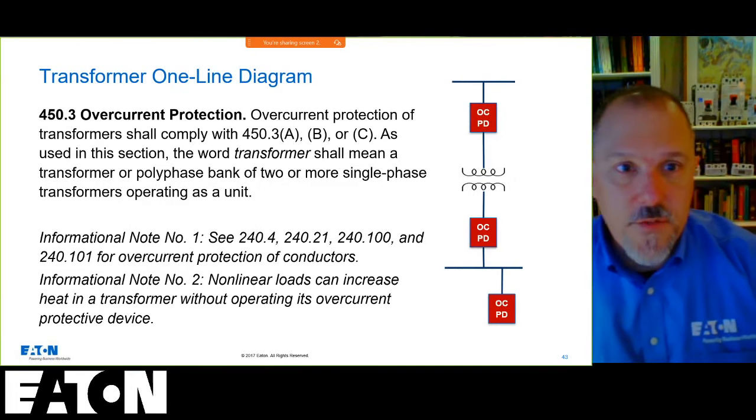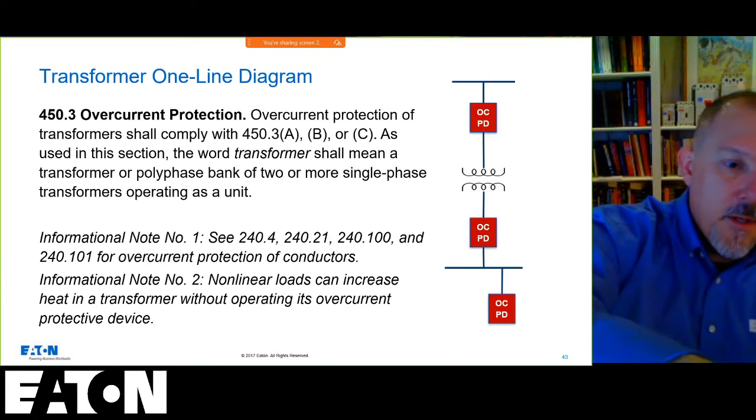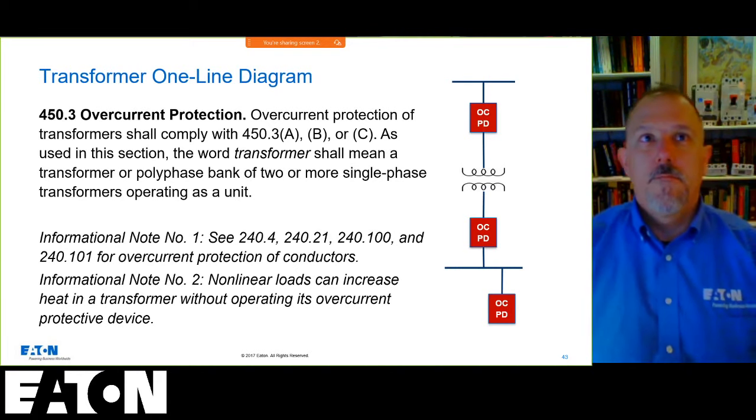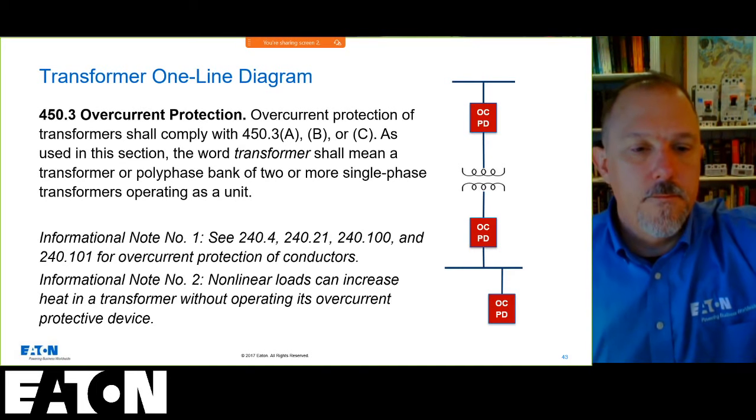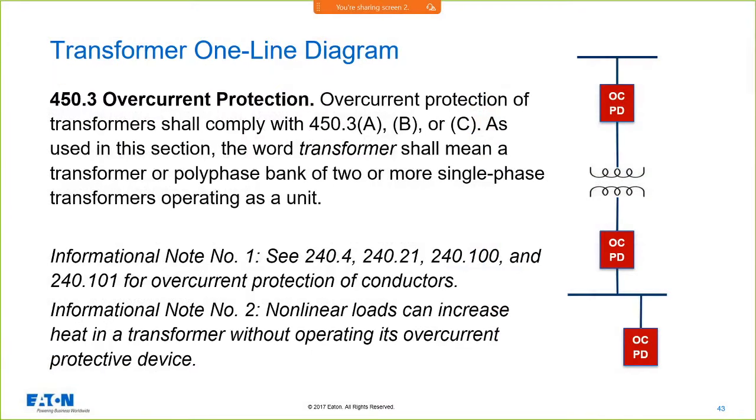Now we're going to reference 450.3 of the book. 450.3 of the book, so the great book of the National Electrical Code, tells us that we have to have overcurrent protection in accordance with .3A, B, or C. And again, and then they restate the...